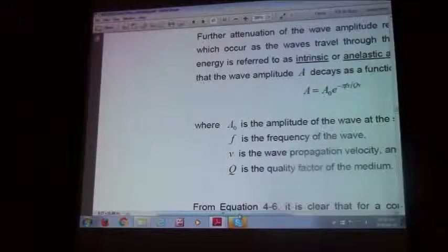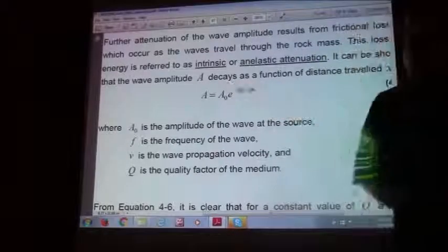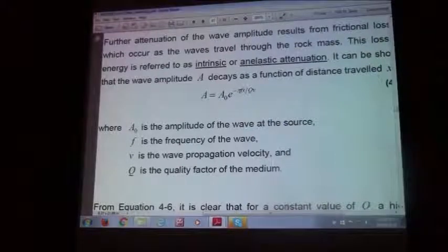Other important parameters that we have to deal with over here is the change in amplitude. What we want to do over here, and that equation just tells you how your amplitude varies with distance as a function of your geometric spreading, but also as a function of your attenuation of the Earth, or Q. Now this is something also that when you're working in the mine, in particular when you've got excavations around, your rock mass can be fractured and damaged. You can get big variations in that Q value. And so when you're trying to determine the size of your source, the amount of energy or moment released, you have to take that into account as well.